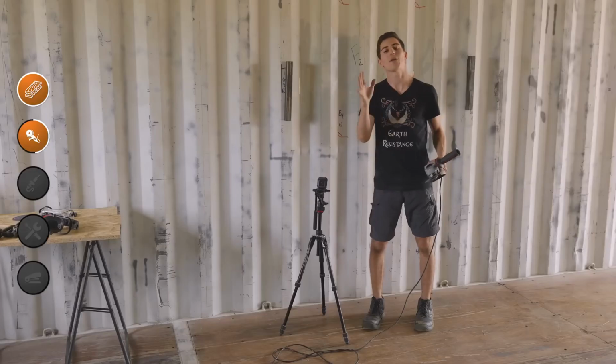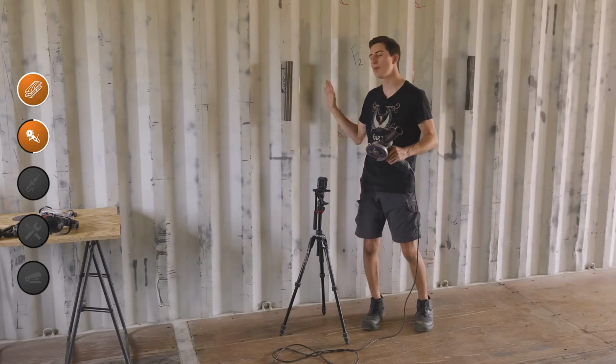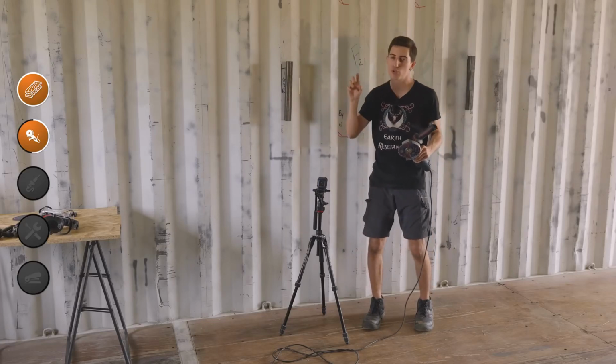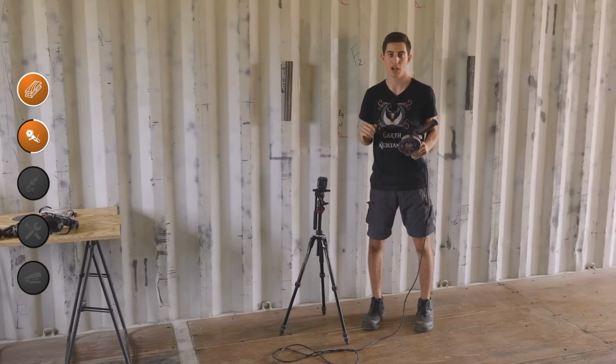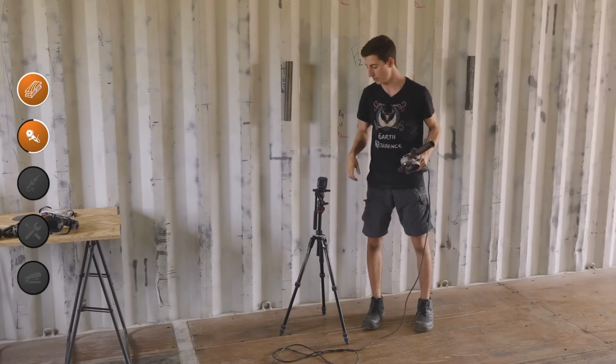Okay, here we took exact measurements down to the millimeter, but let me give you a little tip. It's better to cut a little wider and fill in the gap with expanding foam if needed, rather than cutting too small and then struggling to fit the oriented strand board tunnel in there.